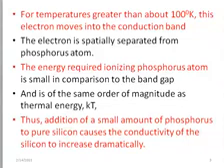So the amount of energy that is required for ionizing electrons from the phosphorus is small compared to the band gap energy, which means since the electron is already mobile, we require a smaller amount of energy to finally push the electron into the conduction band, and this energy is proportional to the thermal energy, which is given by kT. We know k is Boltzmann's constant and T is the absolute temperature in Kelvin.